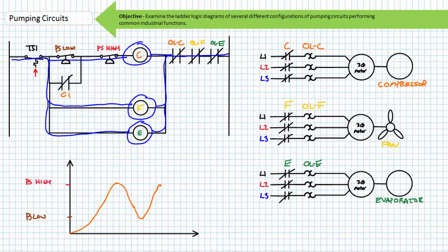Note that as long as temperature switch 1 is closed by an ambient temperature in excess of its set point, the compressor stays inside an operational range, bouncing between low and high set points, and the fan and evaporator keep fanning and evaporating as intended. The coordinated activity of these three devices cools the space and keeps everyone happy.